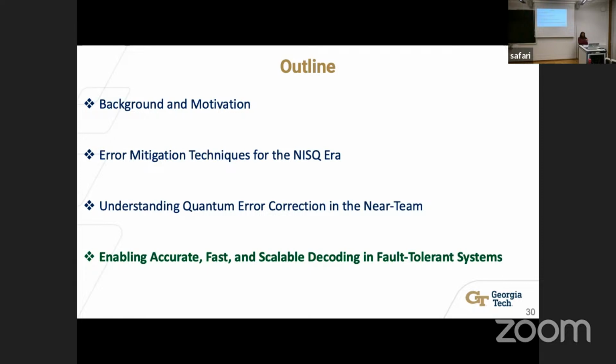For my second internship at Microsoft, the first one in which I looked at error correction, that was in 2019, is the next work I'll talk about, which does that, a silicon ASIC. I won't say can't do, but at least we did not look at minimum weight perfect matching for that, because we were looking at slightly more future systems where the error rates are lower and you can use a more approximate algorithm than minimum weight perfect matching. For near-term error correction studies, given the error rates and the fact that you are still working on very noisy systems, you wanted to build the most accurate decoder you can. In fact, if you look at a recent surface code work from Google, they used multiple decoders depending on the errors. So it's kind of dicey in that sense.